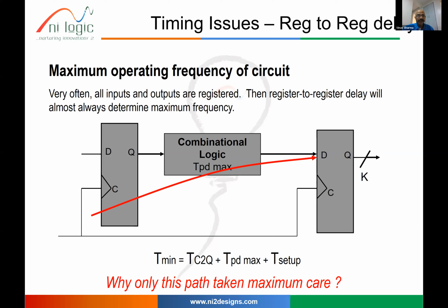So this is done on this timing path. This is one timing path in any design, in RTL design also, which is called clock to setup. It starts from the clock pin of the first stage flip-flop and ends at the D input of the next stage flip-flop.